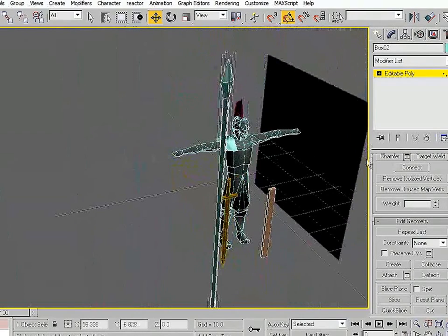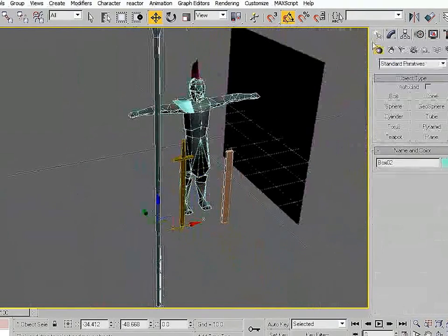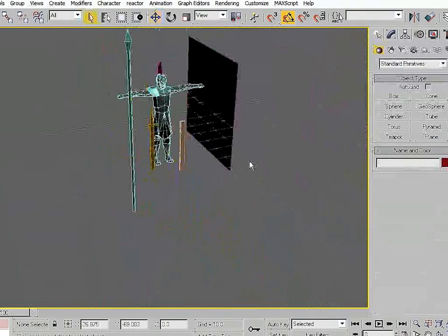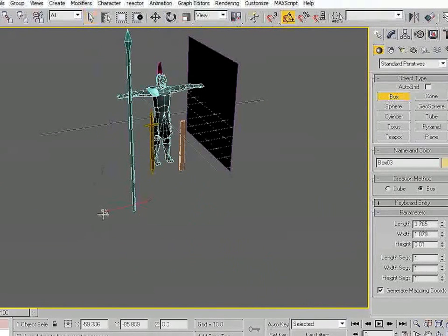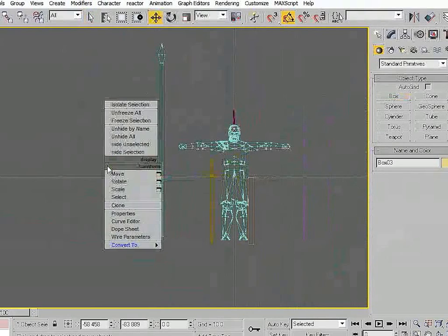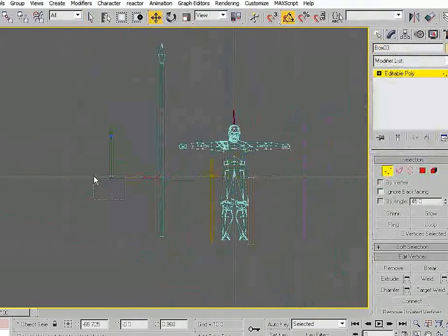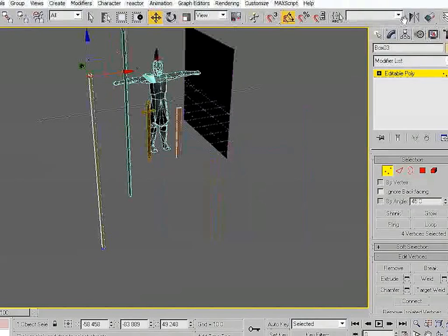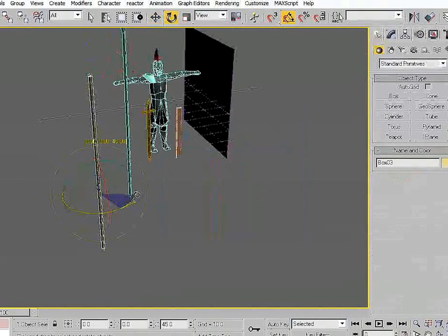It's real easy, and the standard is essentially the same thing for just a pennant standard like that. Just make your box 1 by 1. Again, go into your front view, to an editable poly, figure out how high you want the standard, rotate it 45 degrees, since you want to approximate a circle.